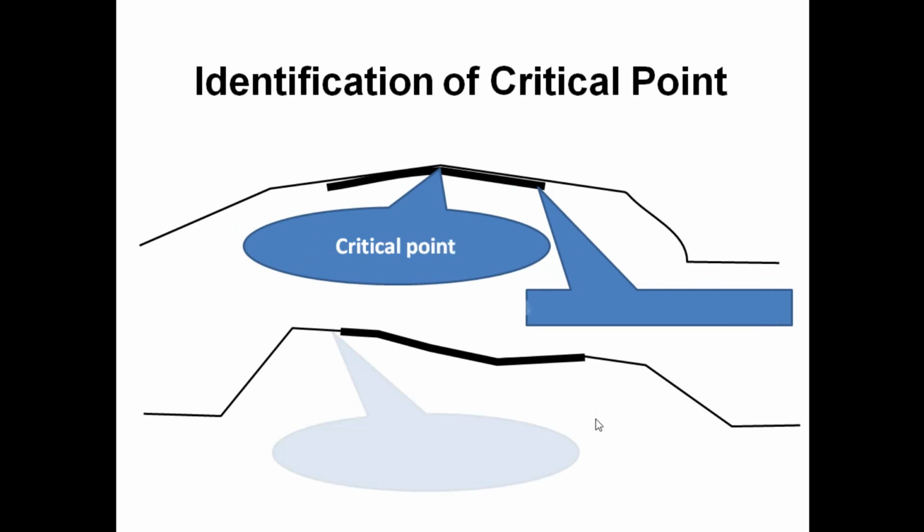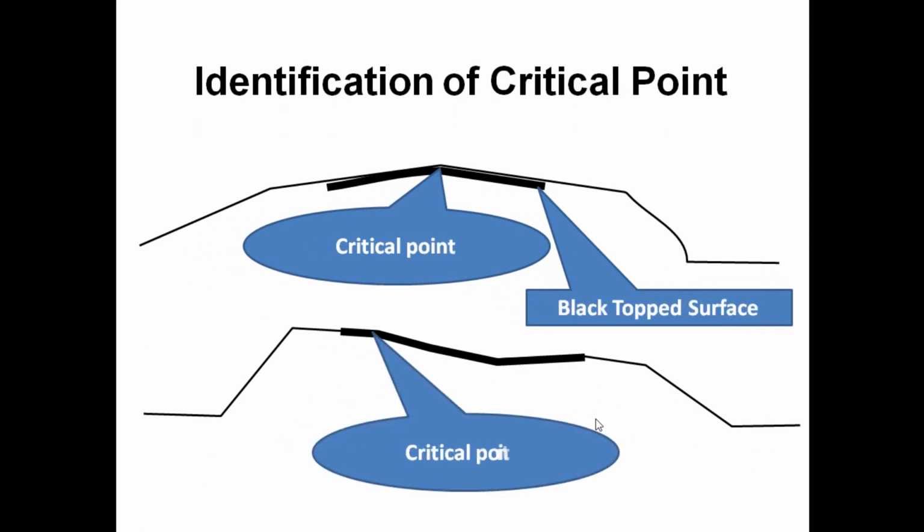Firstly, it identifies the critical points at every cross section, then analyzes each cross section, then creates a baseline on the profile or the vertical pattern in such a way that no cutting is involved and all the specifications of the IRC are followed to get the best results. Unless the user changes the parameters, the designed vertical profile will be in line with IRC standards. All these computations, posting back values, and optimizing the vertical alignment happen almost instantly.